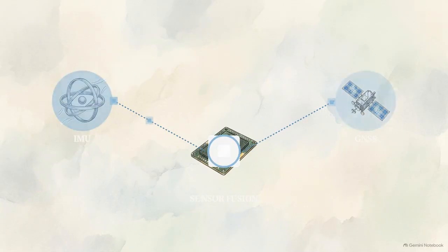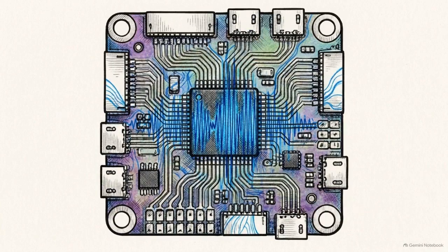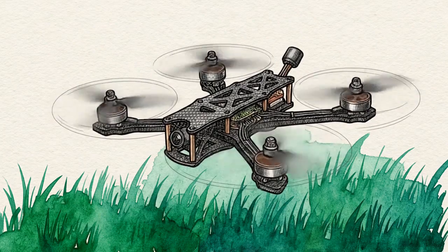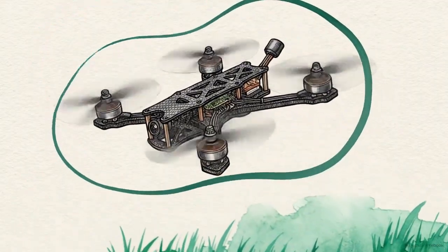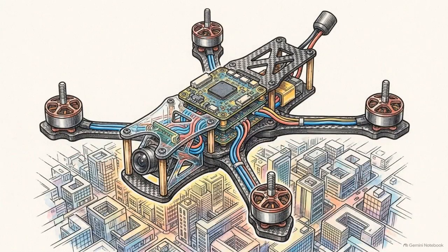logic process restarts. This continuous circuit, sense, decide, act, fly, repeat, is the closed-loop control system. To maintain flight, this loop must execute hundreds of times per second. If latency is introduced, whether from a slow processor or electrical interference, the drone will fail to correct its error, resulting in catastrophic oscillation. UAV autonomy relies on the precise, high-speed synchronization of rigorous hardware isolation and mathematical control theory.